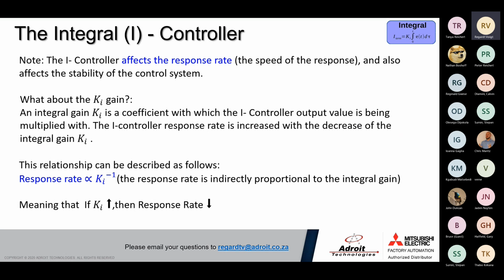That's why you have to have a perfect balance depending on your application. If you want something that's very accurate, it will be slow. If you want something that's very active in reacting to errors, it will give inaccuracies due to overshoot, undershoot and steady state errors. So a balance needs to be achieved to give the best error correction over time.